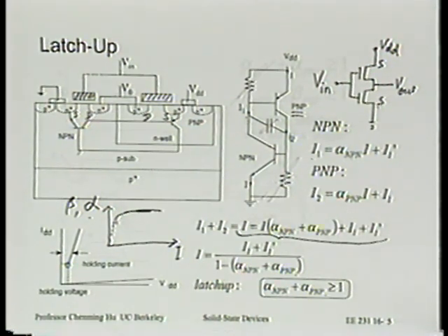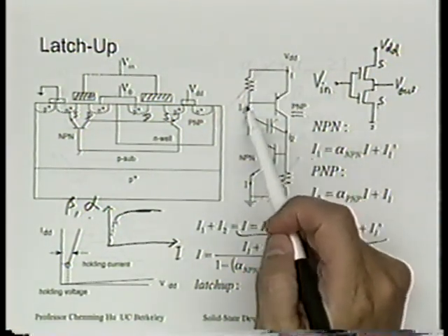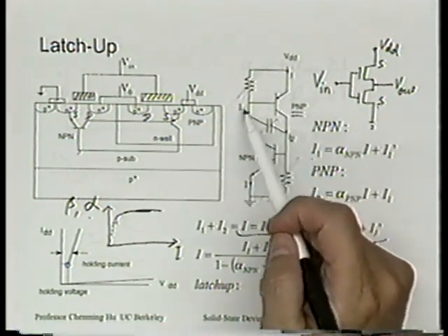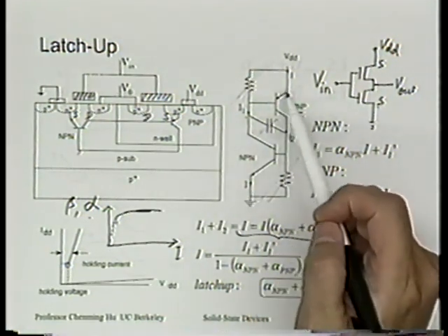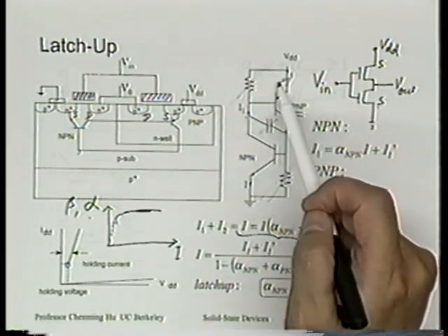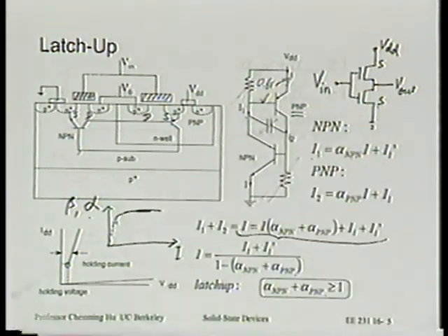Well, you do that by realizing that if I can short circuit the base and the emitter, then I basically take this transistor out of commission. We don't have a real transistor anymore. In order to have a bipolar transistor operating, we have to have this emitter-base junction forward biased, say 0.6 volt. Is that right?